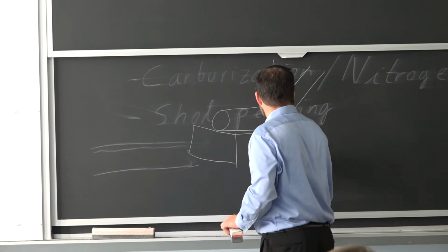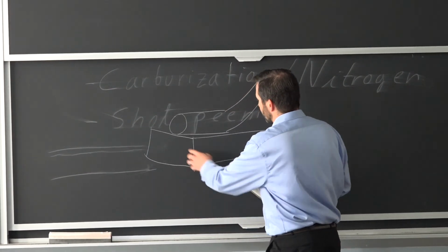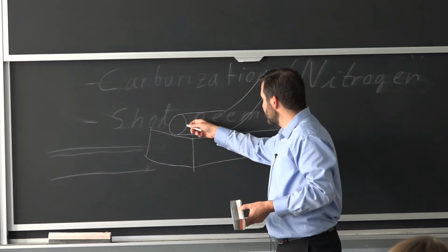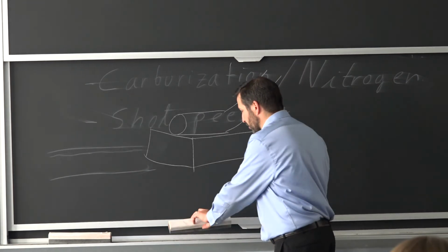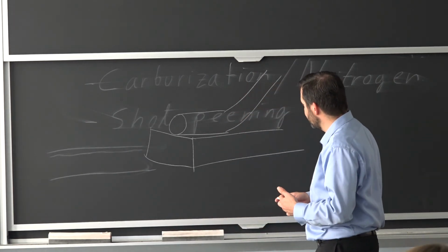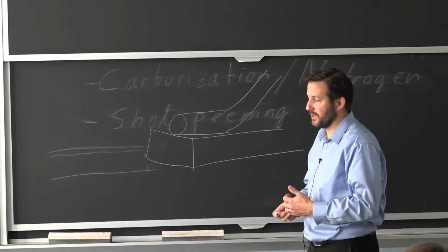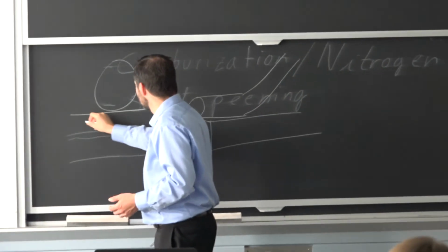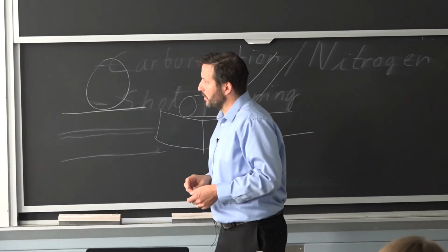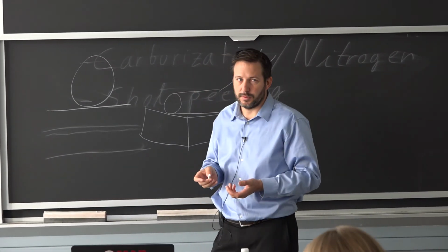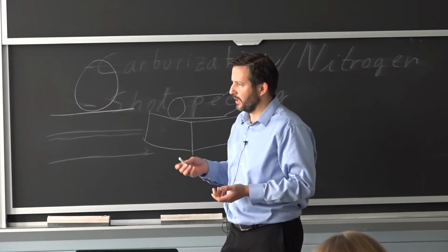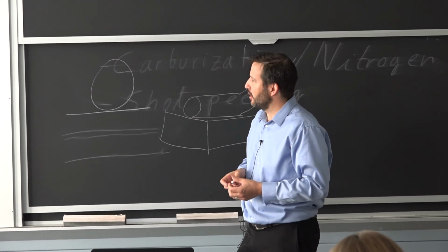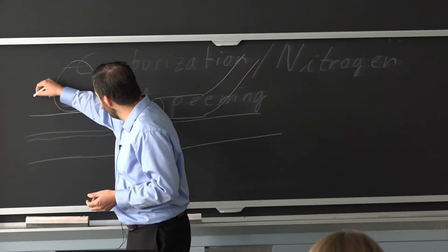So it's kind of a special case where one surface is flat, the other is curved, and you try to weld between them. Not ideal, but what happens is these bars are effective in terms of weight, and therefore, if you're able to weld them good enough, you do. So it's a difficulty because of the access to weld between those two surfaces, but you'll see a lot of times the structures for roofs on buildings, and this one was in a big greenhouse, a 25-acre tomato greenhouse. What happens is you can align your torch.